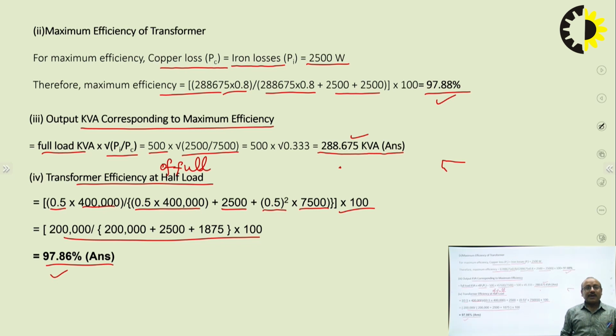And one more important point in this, if we operate a transformer without any load or on no load condition, efficiency becomes zero. Since no load means no current, no power, so output power becomes zero, copper losses become zero due to no current, but core losses remain constant, and efficiency is output power upon input power. When output power becomes zero due to no load, that means no current, no power, so the efficiency of the transformer becomes zero at no load condition.